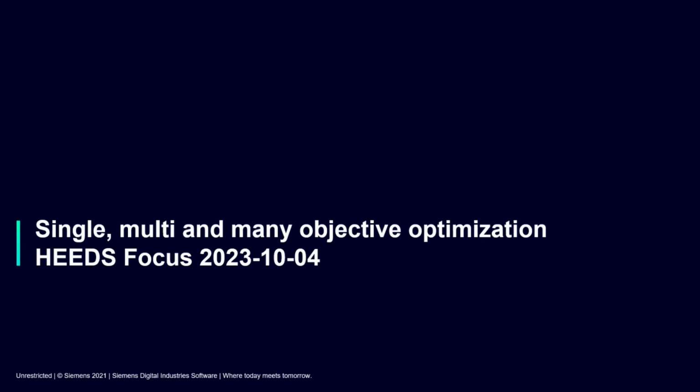So for single objective optimization, I personally usually try to have 50% more generations than individuals. So in my example, I would have 40 individuals in my population and then 60 generations, and then get my 2,400 evaluations.